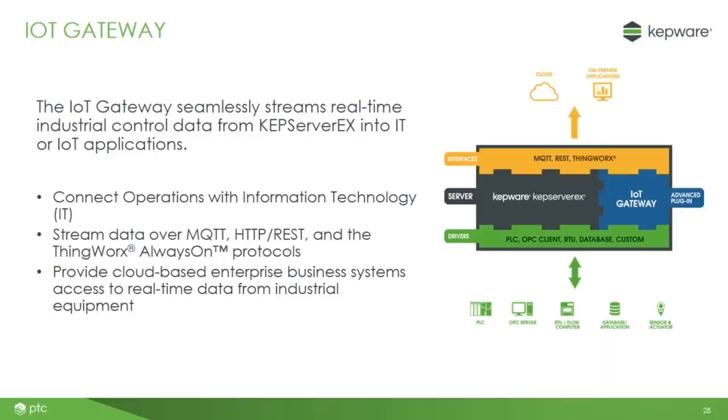So just in my example, you saw me take a piece of data and load it into a web server. I didn't have to do anything complicated or scripted to do that because I leveraged that normalization layer. The IoT Gateway plugin plugs right into that normalization layer, and so the tag objects from the ControlLogix device can be accessed just with the graphical browsing window. Now that the data is normalized, I don't need to care where it comes from, really. It's interesting where it comes from, and that's useful context, but it doesn't matter to me technically. So I can have an easy user workflow that just says point to this object, bring it in the gateway, and then make it available. Boom. So we have these layers of KepServer. We've got a driver layer, a server core that normalizes data from all these disparate systems, and then we have interfaces on top for publishing and accessing the data.